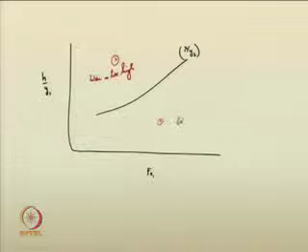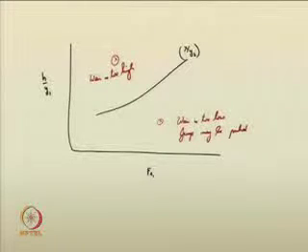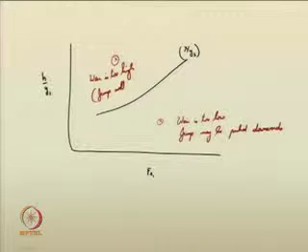So, the weir is too low, and the jump may be pushed downwards. Further downstream the jump will be pushed, or it may get washed away also. In this case the jump will move upwards. So, for the following x by y2 condition, if you are providing the h by y1 ratio in the upper cases, this is what will happen. That is the meaning of such curves.